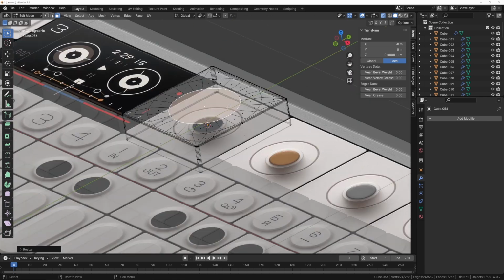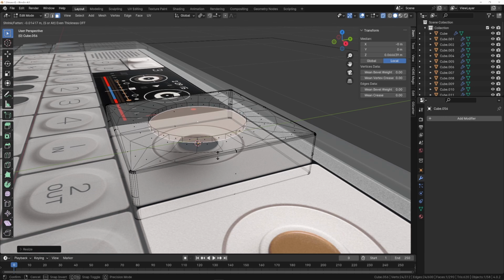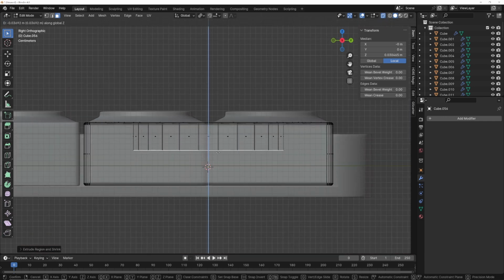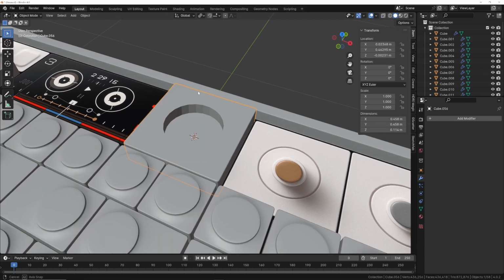So now to make this little spinning shape, we've got this face still selected. So let's go extrude face along normals. Let's just bring this down a little bit. We'll say that this is half as much to where this piece can sit in. Now we've got this modeled.